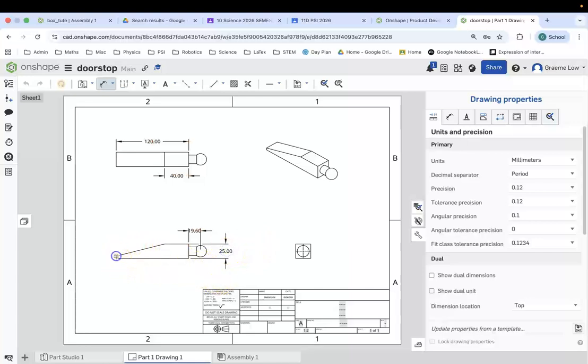And we could put in the height of the little wedgie bit here as being 4. That's probably enough. Oh, we probably just need the radius of the circle as well. So it's a 10 centimeter radius circle. R stands for radius. So that sort of shows us all of the relevant dimensions that someone would need to know if they wanted to manufacture your design or something like that.